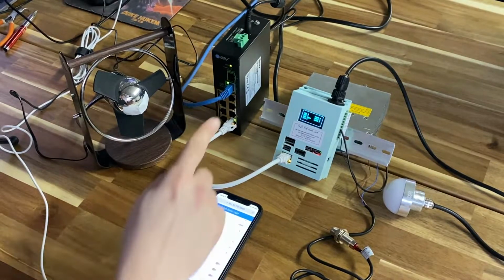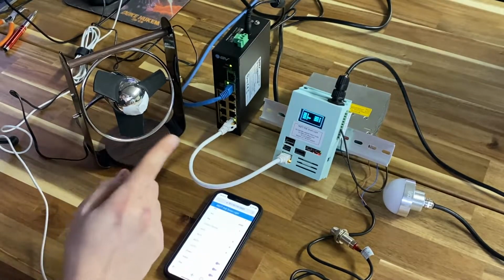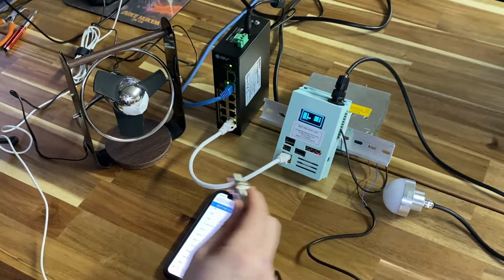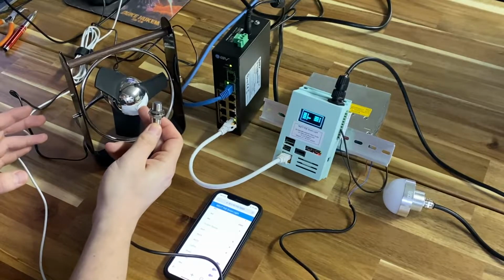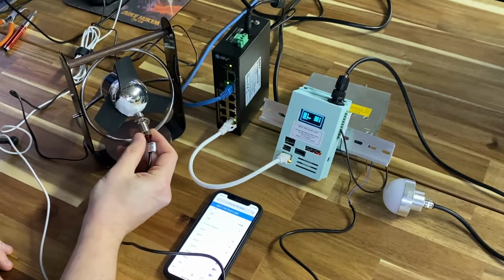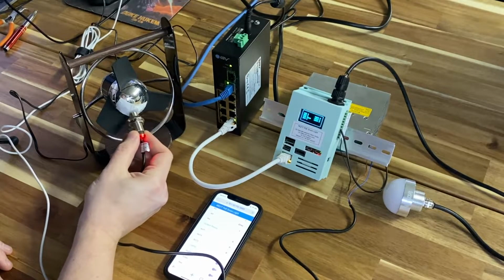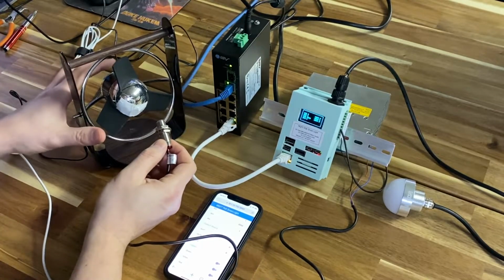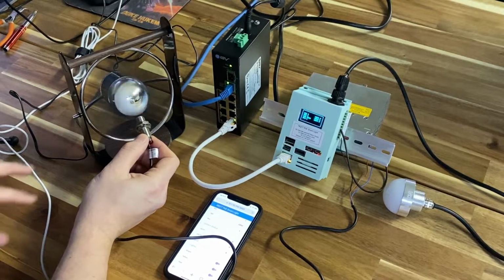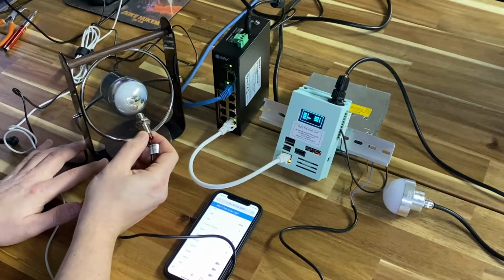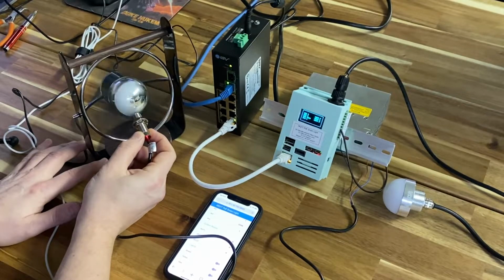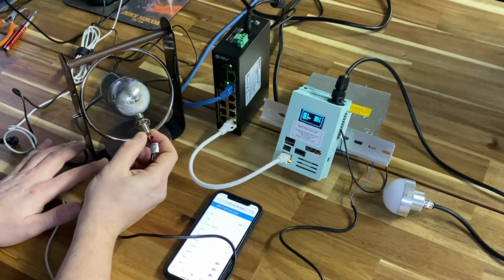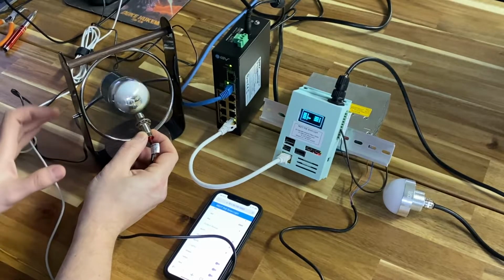So let me demonstrate how the inputs work right now and the theory behind why we use some of the libraries that we did. So here for this fan, if I turn on the fan, I have a magnet attached to the fan here, which triggers the sensor to send the signal, right? So you can see it counting in here. Because of the libraries that we're using, we're able to count the inputs at a very high rate. So you could use something like this to count the pulses on an encoder and not be limited by some of the Python logic that's running in the background. And I'll explain that in a minute.